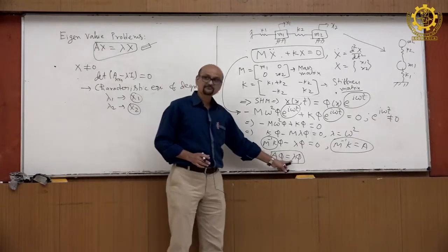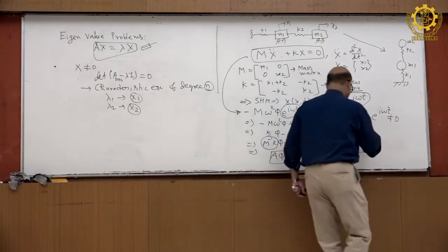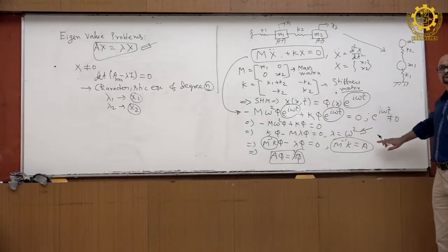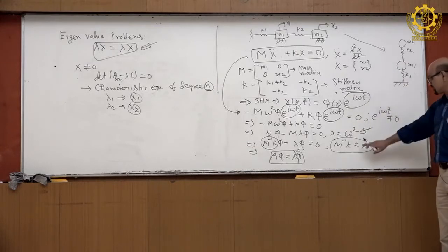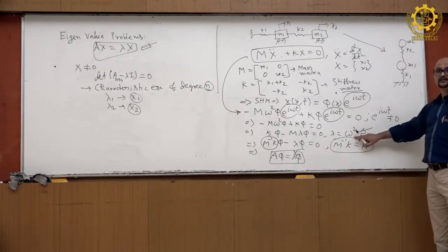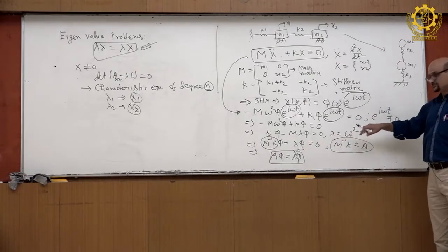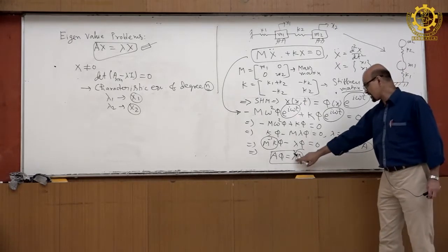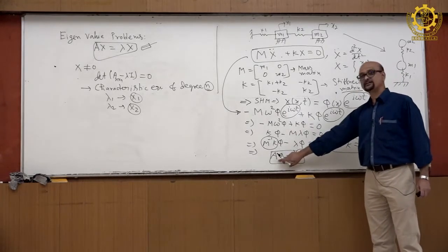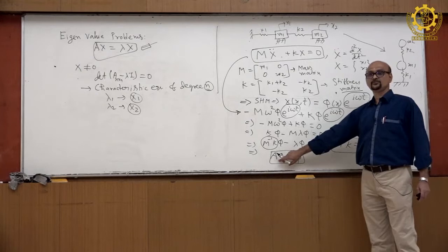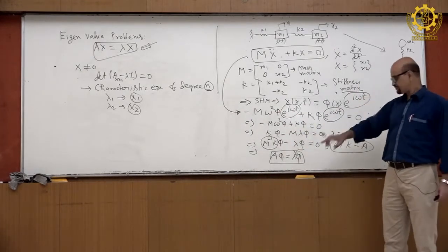So, this lambda I need, why this lambda I need? Because lambda is omega square, that means frequency. For the design purpose, I need to have this omega. So, if I get lambda from there, I can find the omega. Similarly, if I find lambda 1, because how many lambda depends upon the matrix order, whether it is repeated or not depending upon the matrix type.